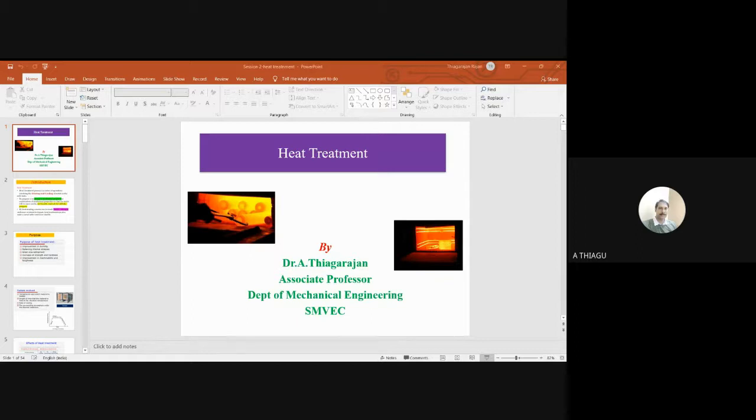So what are the techniques or methods available for surface heat treatment process? I can say the first one is diffusion. Diffusion means you are going to deposit carbon and nitrogen. The terms are carburizing process, nitriding process, cyaniding, carbonitriding. The other method is called thermal process or thermal methods. One will be flame hardening and the second will be induction hardening. Flame means thermal heat treatment by means of oxygen acetylene. Induction means through the help of current.